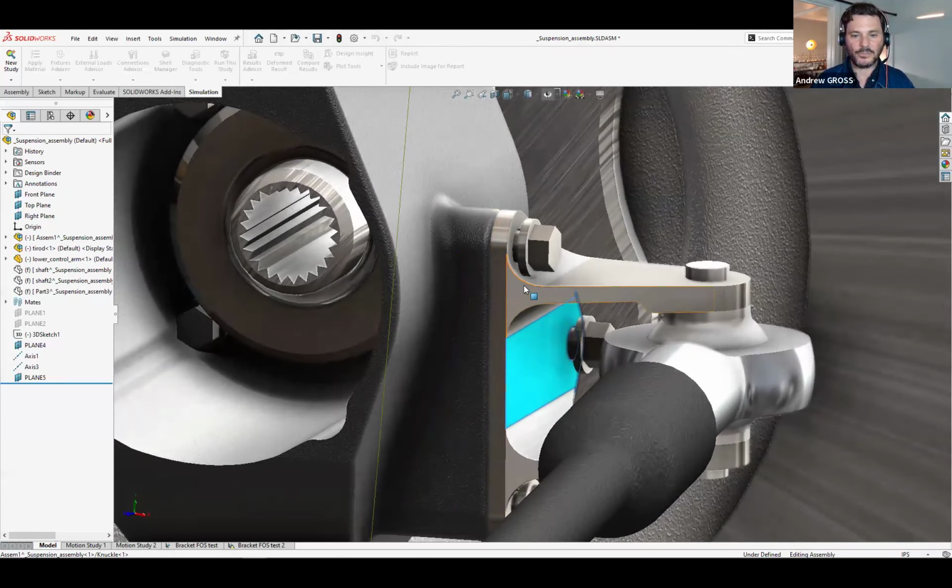What a virtual wall does is it emulates the fact that it's against that wall. A roller slider would say that it can't do this. A roller slider means it's stuck to that wall. It can move along the plane of the wall, translating in two directions and rotating in one direction. So a roller slider removes 3 degrees of freedom. A virtual wall says, well, this can bend like this. It can swivel, but it can't go through that wall. So it's actually a lower grade fixture, which is more realistic.